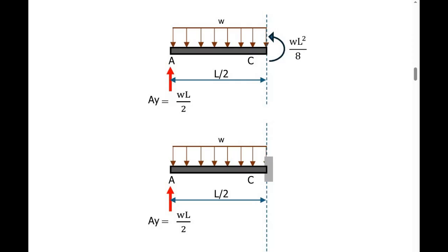This is what we call the M over EI diagram by parts. Using an equivalent cantilever beam, the idea is to make the beam act as a cantilever beam to have areas and centroids of areas under the M over EI diagram that can be easily solved by using formulas which are familiar and easy to remember. Since we need only the area between A and C, we consider only the portion of the beam between A and C by cutting the beam at the midspan.